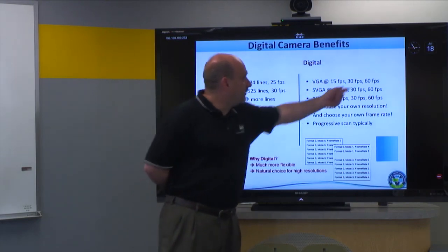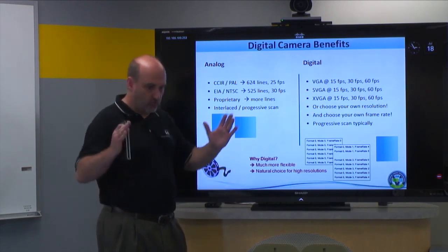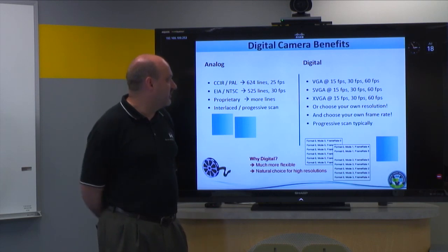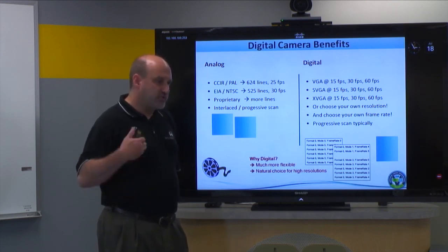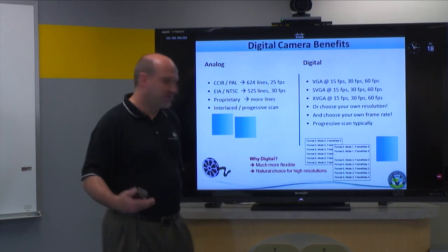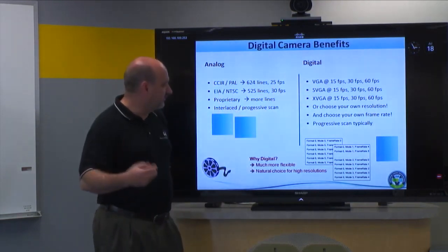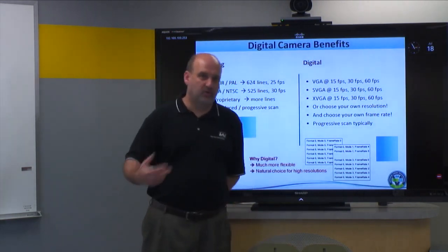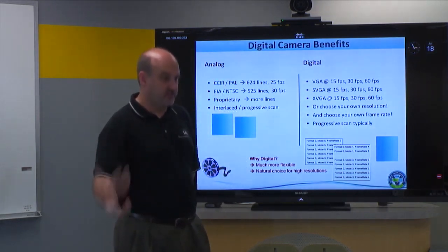The frame rate might be different as well, not only the resolution, the aspect ratio, whether it's a 1:1, a 4:3, wide HDTV, which happens to be 16:9 aspect ratio. Those are all varying things that we have to deal with on the capture end, but in the digital world, we just deal with those in the interface standard. So we make a standard that takes care of all these, and in most cases, and we'll talk about the standards, either the format is predefined or it's flexible, and the camera says, I have this many pixels horizontally, I have this many vertically, and the digital device configures itself.